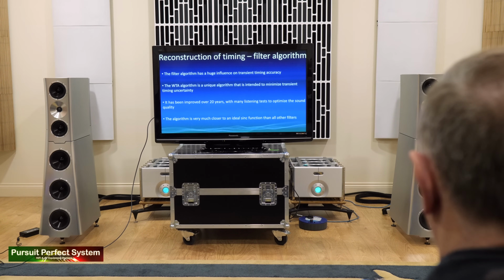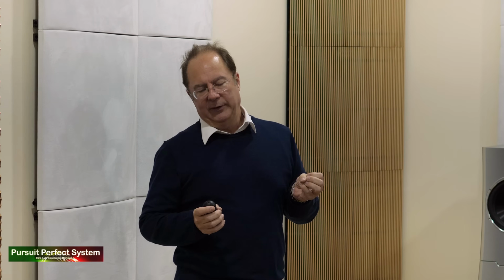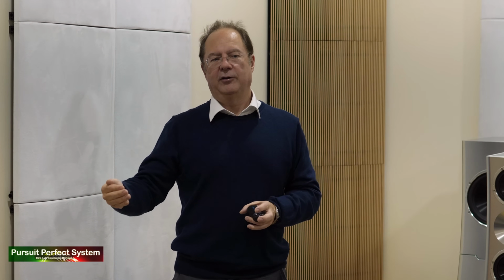The filter algorithm, the algorithm itself that is used to reconstruct the information, has a big difference on sound quality. And when I first started playing around with this, going back to 1999, when I had my first WTA filter, I started off with a long tap length filter. In those days it was 1,000 taps. Conventional filters, only 100 taps. 1,000 taps was the maximum I could do with the FPGA technology that was available. But what I found was that if I changed the algorithm, I would get better reconstruction of transients and better sound quality. And that led to the WTA algorithm.